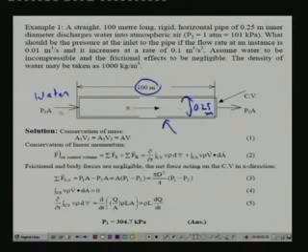And the water enters at certain pressure and it leaves at a pressure that is equal to atmospheric pressure. That means here you have P2 is equal to 1 atmosphere. So basically the pipe discharges water into atmospheric pressure, and at a given instant the flow rate is 0.01 meter cube per second. That means the flow rate of water through the pipe at a given instant is 0.01 meter cube per second, but it increases at a rate of 0.1 meter cube per second square. That means the flow rate through the pipe is not constant, but it increases with time, and the rate at which the flow rate is increasing is equal to 0.1 meter cube per second.